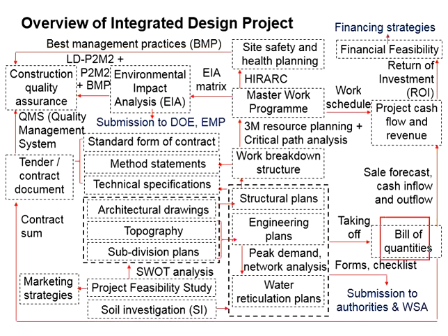Based on the bills of quantities, the contractors shall bid a price to be considered by the employer, for the employer to select the best contractor to carry out the construction project. Summing up the costs in the bills of quantities gives you the contract sum. Among several contractors who bid for the project, the employer shall choose the one deemed to be giving the best offer to be awarded the contract.